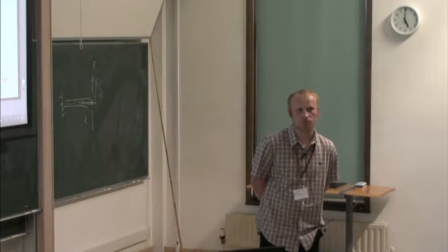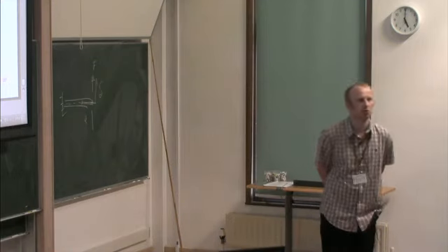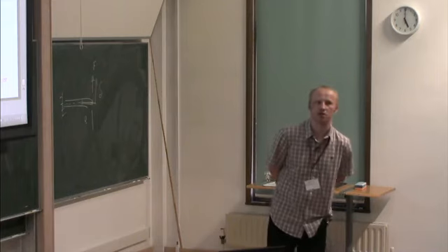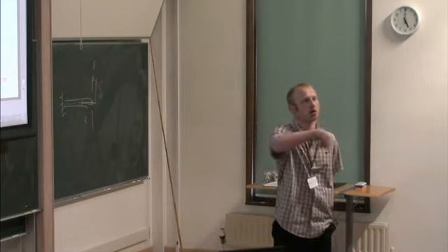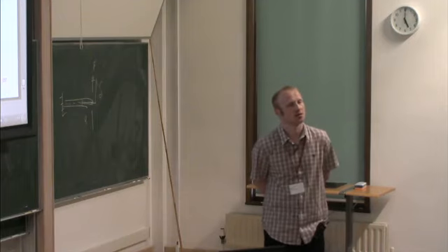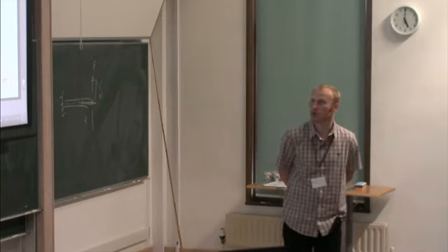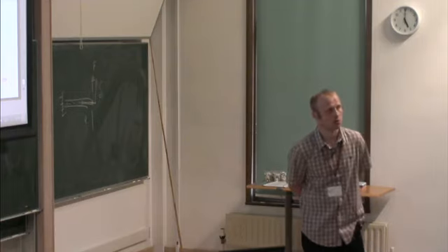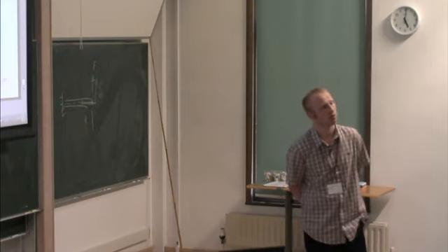In 2D, typically we can take epsilon 1/64 pi. This maybe says something to people who are familiar with the model. And that means for this problem we take a mesh size that is 1/256. So if you have a square 1 by 1, then you divide it by 1/256. In 3 dimensions, that's quite a bit less. There we can, let's say, comfortably handle problems where we have a mesh size of order 1/32 to 1/64.